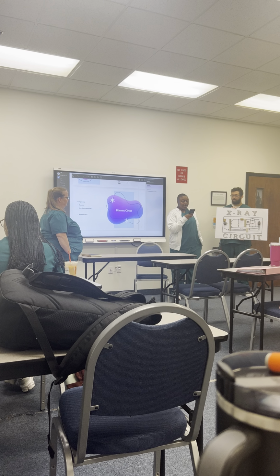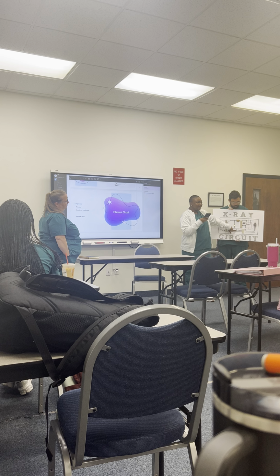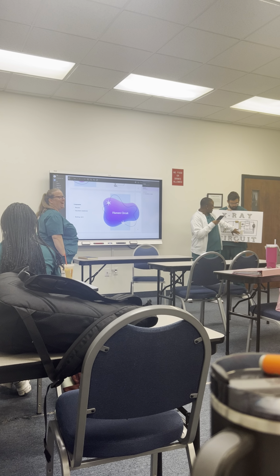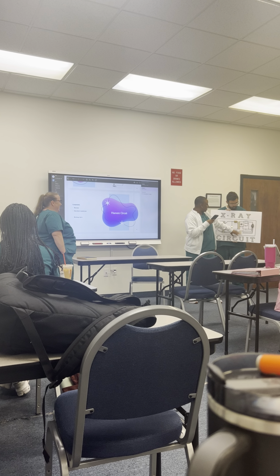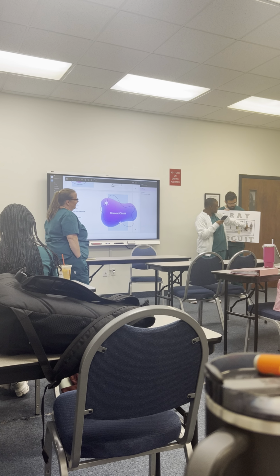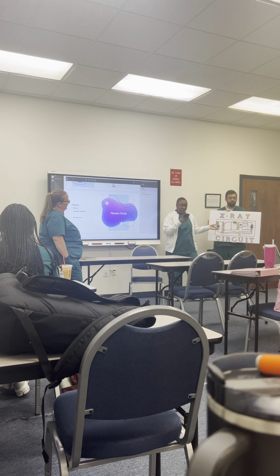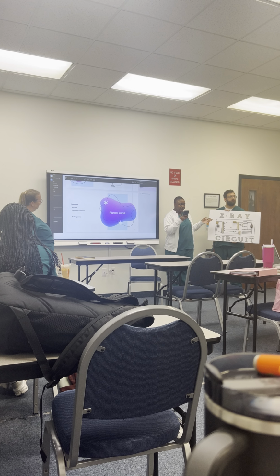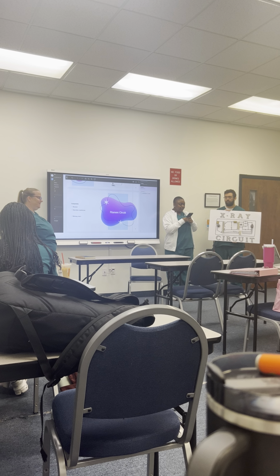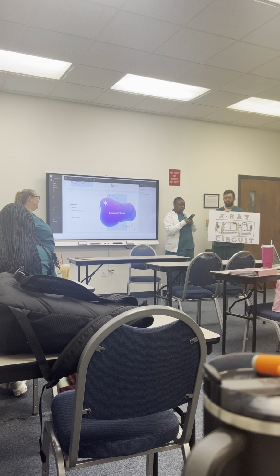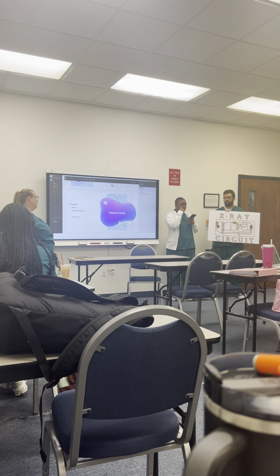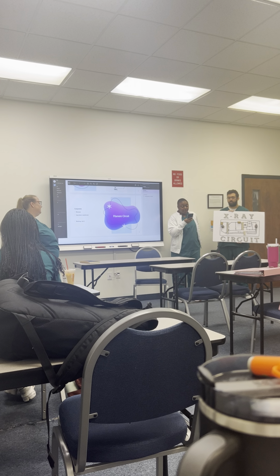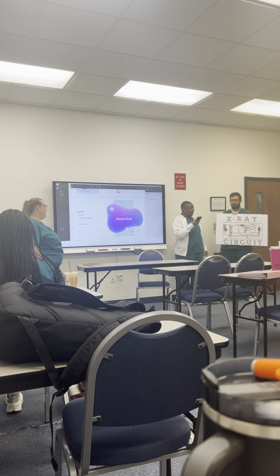So, this is my step-down transformer. This is my little rheostat. Isn't she cute? And then once everything is increased here, it flows to the X-ray tube and it heats up the filament and starts the whole boiling process, thermionic emission. If the rheostat malfunctions, it could cause a disruption in current control or even circuit damage if the resistance comes too high or too low.